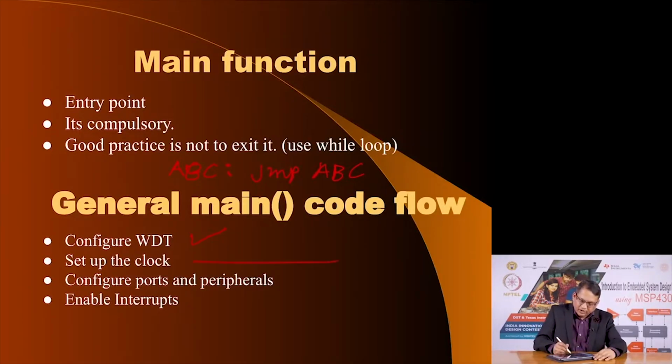Then a microcontroller and especially MSP430 has lots of options of the various clock signals. So, you need to set that up if you choose to. If you do not set it up, the MSP430 works with some default clock which is usually born out of the DCO and the frequency is 1.1 megahertz, and I am talking in the context of the MSP430 G2553 microcontroller.